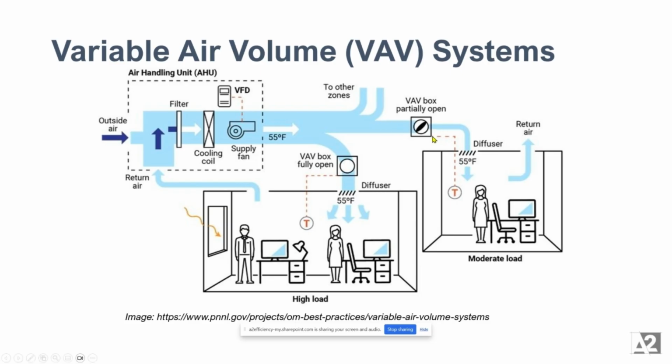So the amount of air and the level of heating is controlled by the zone's thermostat, and then all the boxes together send signals back to the air handler and determine what level of cooling is provided and also what level of airflow, right? It's sort of a number of things. We're not really here to talk about the interactions between the air handler and the zone. We're really here to talk today just about the zone and the flow needs required.